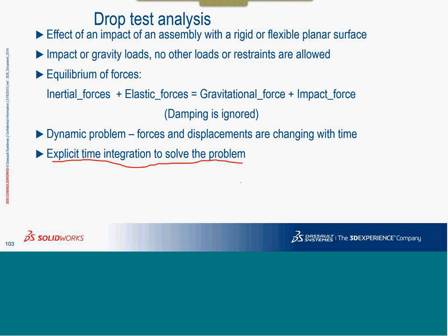So you will have many geometries which need a comparatively large number of elements, and when you start solving them in our module, you might see times of 10, 20 and 30 days as well, and it makes no sense to use that module for a particular product unless you simplify the geometry, make it very simple and get it going. So it has its own good and bad points.